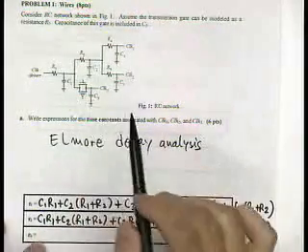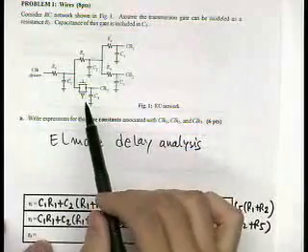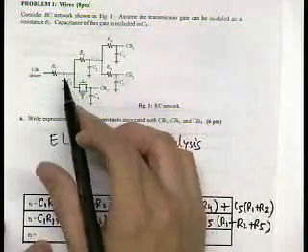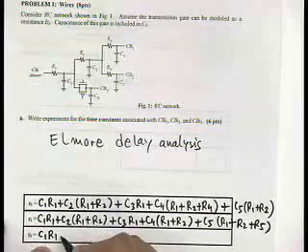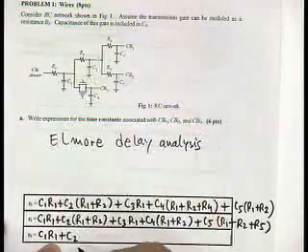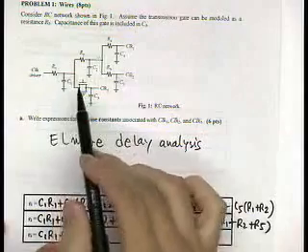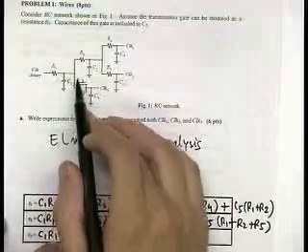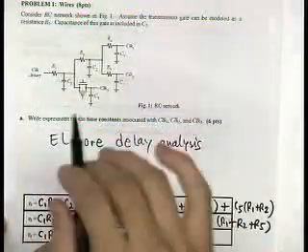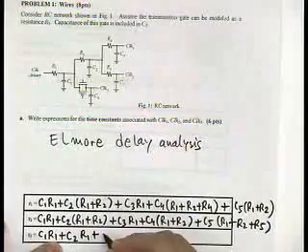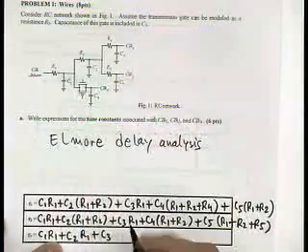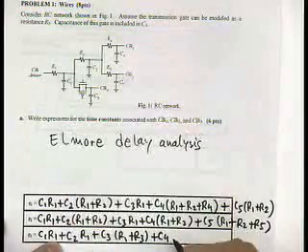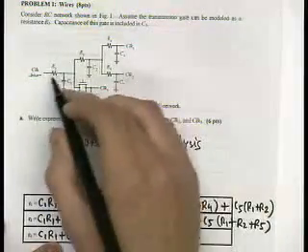And then finally, for this path, you had this transmission gate, which was nothing but a resistor. And we said that the capacitance was also lumped into this C3. So for this one, C1 sees only R1. C2 also sees R1. It is much similar to the example we did in lecture. If you remember, we discussed the situation when you had the side load and you were only interested in what's happening at this capacitance, and you had to include all of these. And then C3 was R1 plus R3. C4 had only R1, and C5 also only R1.